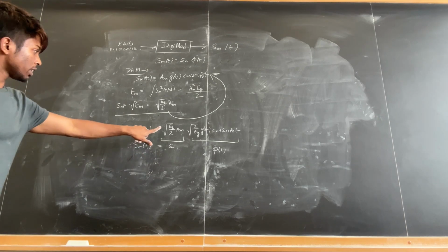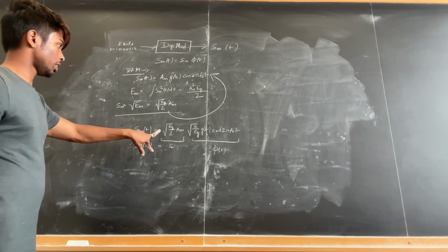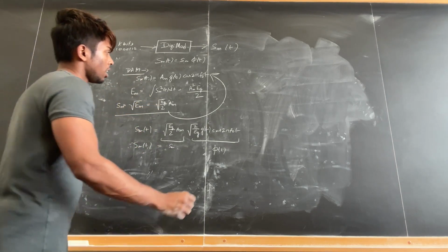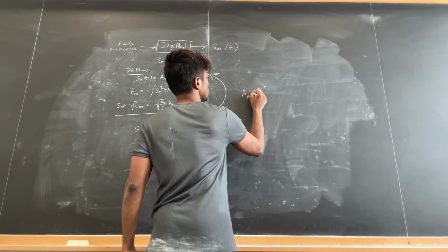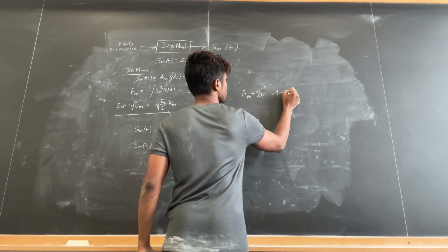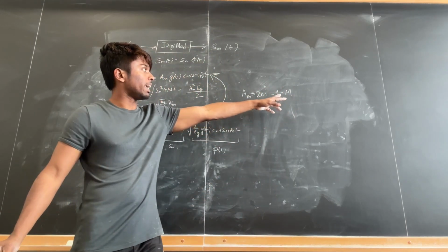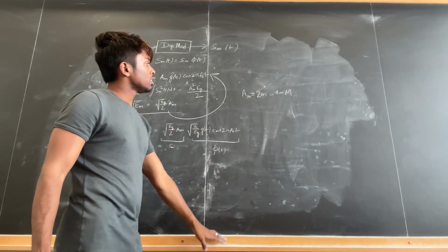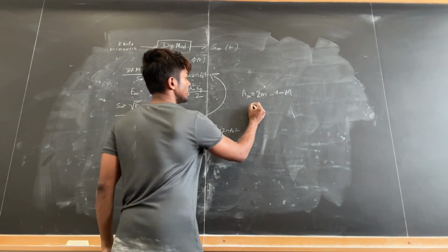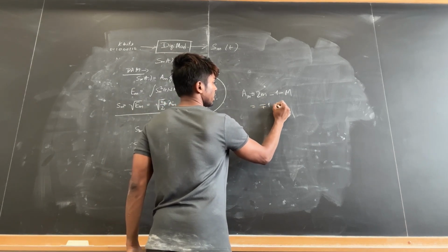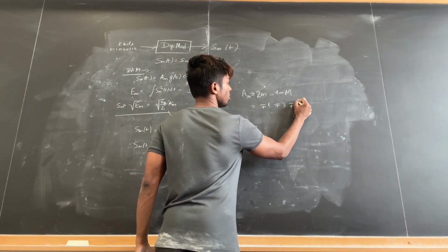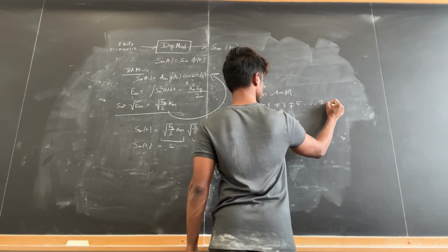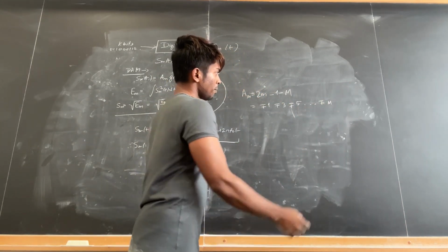So from this we can generate our constellation diagram, but we must also specify how Am varies. So Am varies as 2m minus 1 minus capital M for all the possible symbols m, and this is the variation of Am. If we expand this idea for all the symbols, it comes to minus plus 1, minus plus 3, minus plus 5 and all those odd values until minus plus M minus 1.